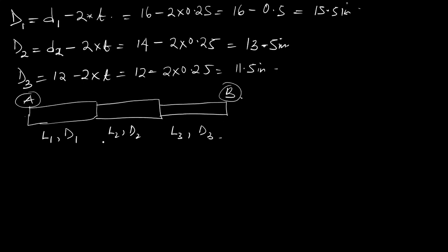Now we are asked to find the inlet pressure, when the delivery pressure was given. When you check, the diameters are not the same. Since the diameters are not the same, the way to solve this is to convert the second segment to have the same diameter as D1. Also the third to have the same diameter as D1, with an equivalent length each of them.